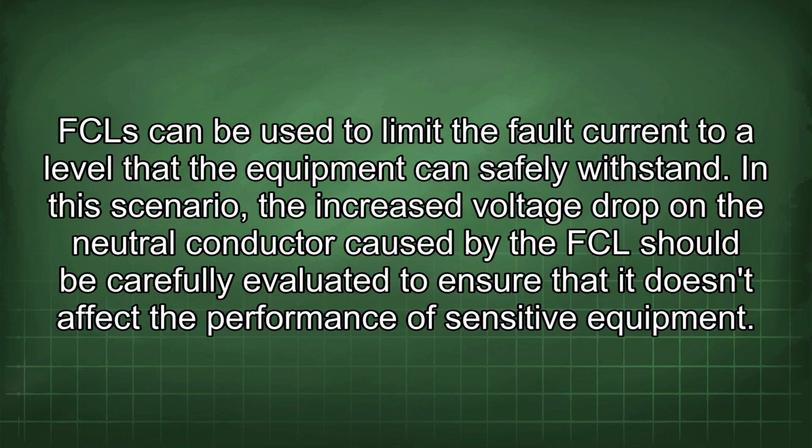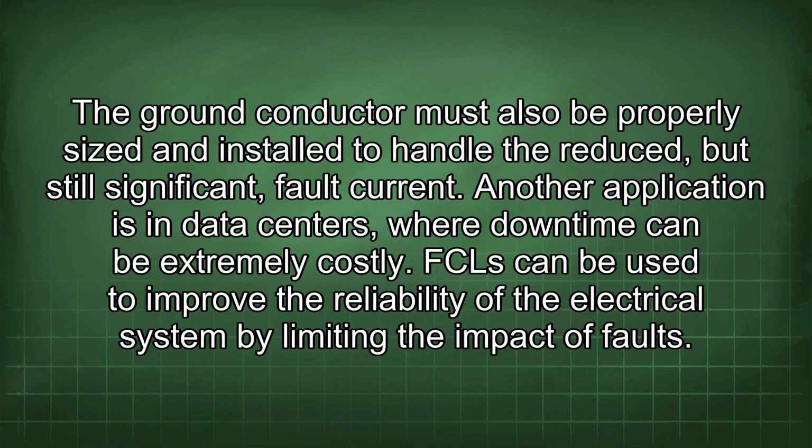In this scenario, the increased voltage drop on the neutral conductor caused by the FCL should be carefully evaluated to ensure that it doesn't affect the performance of sensitive equipment. The ground conductor must also be properly sized and installed to handle the reduced, but still significant, fault current. Another application is in data centers, where downtime can be extremely costly. FCL can be used to improve the reliability of the electrical system by limiting the impact of faults.